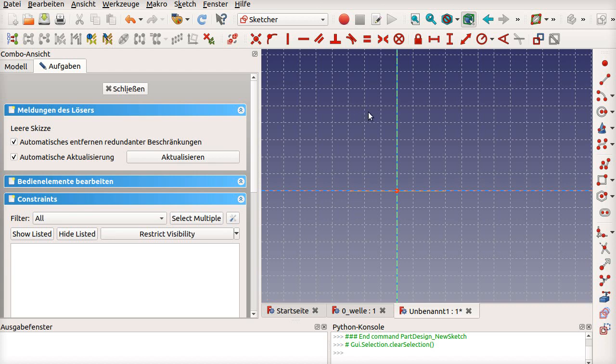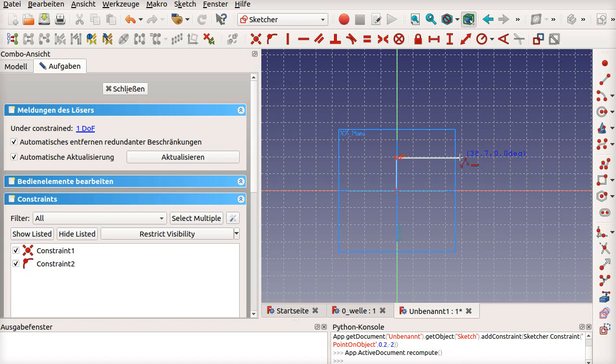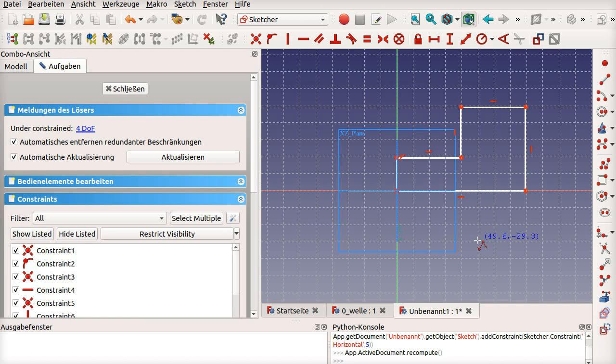Let's use this. If you have a double side shaft, you may use a new plane with a distance to the other side. So I go here, start in the middle, go up using the grid. The grid you can enable in the settings on the side here, or disable it if you don't need it.